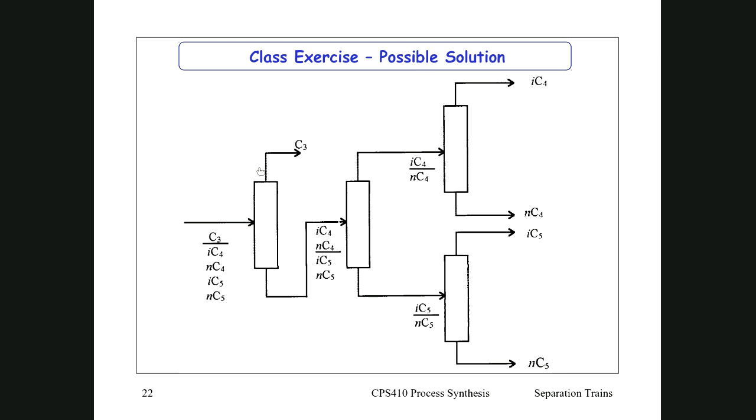What we'd have to do is work out how much each of these distillation columns costs. But it's not just the capital cost. We have to work out how much it costs to run, because you can always make a distillation column bigger, with many more trays, and then you would use less reboiling, less energy essentially, to get the same amount of separation.